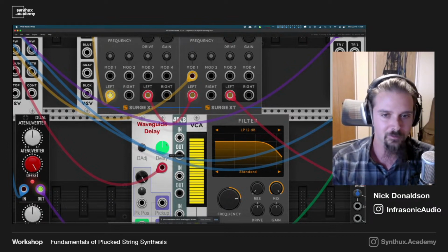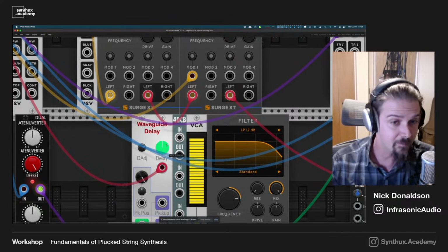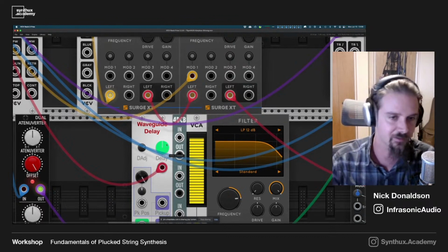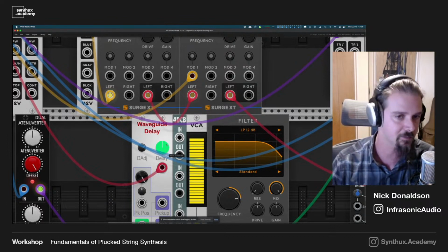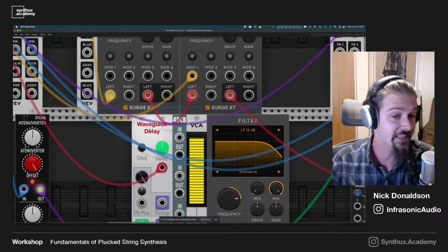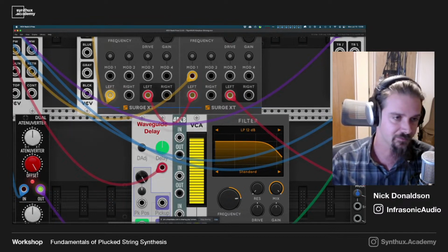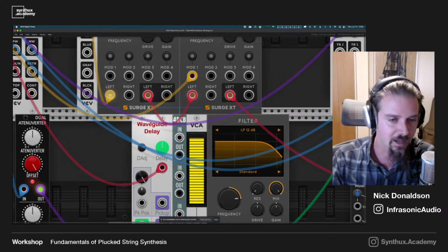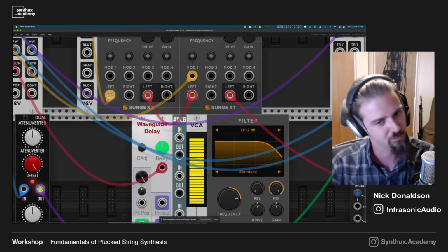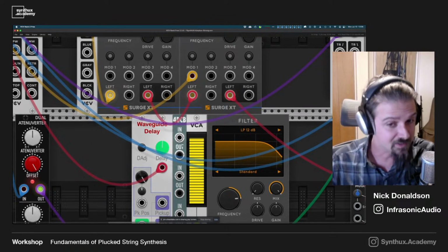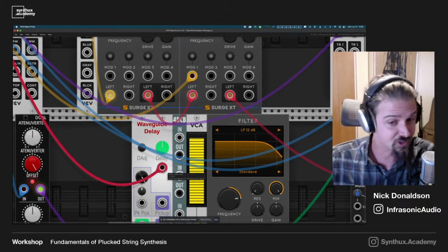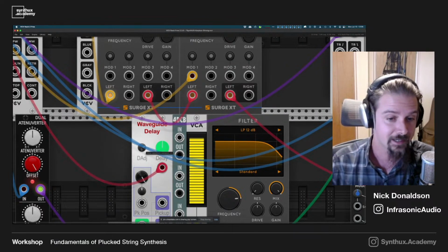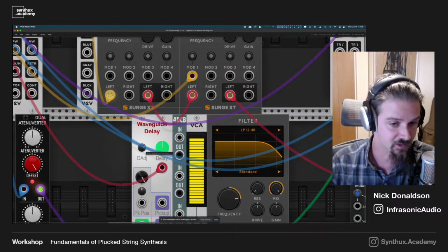The code example that we went through, which I can also make available for download later, does that math, but based on just sort of internal pitches, just going up an octave based on some code. It's not taking external input. This module is doing basically that same math relative to the standards of volt per octave for VCV Rack in order to derive how long the delay line needs to be to get the pitch we want. But that is also subject to what's in the feedback loop, because that adds additional samples of delay in our feedback loop. And then that's what this adjustment control is for, to sort of compensate for however much stuff we put in there.